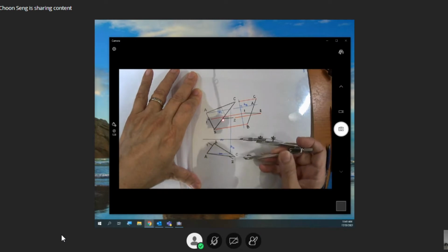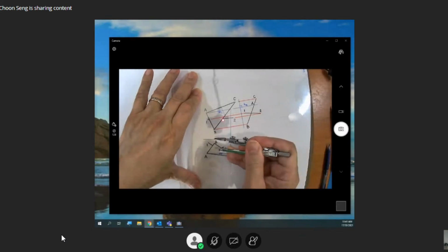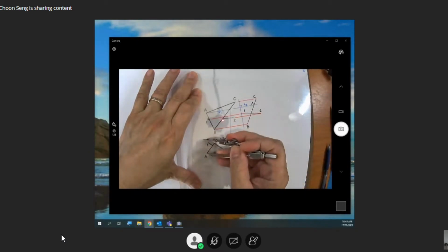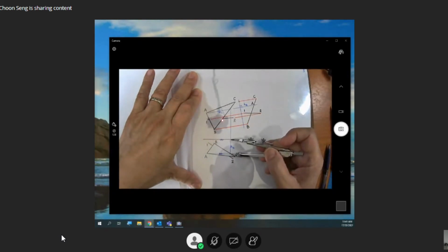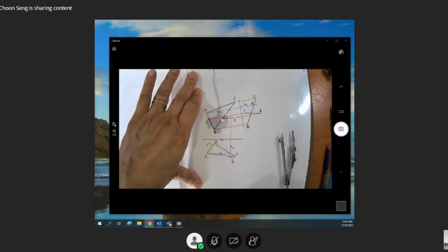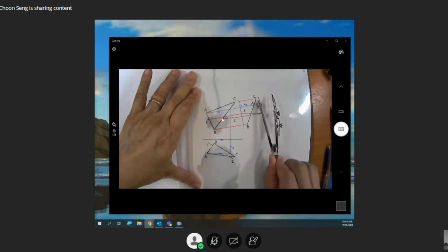All these lines, the red lines, the blue lines are all parallel to your true length. Okay. Your vertical height C, transfer. Your B from here, transfer. Your A, transfer. Okay. Your this A, the other point here, since it's parallel, it should coincide. Okay, if it doesn't coincide means your drawing is not accurate. All right, yeah. So you get ABC, one line, a single line.